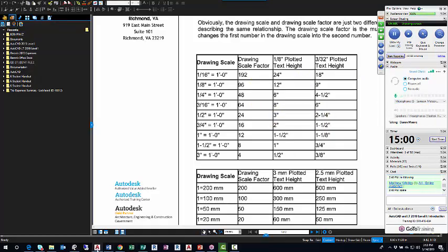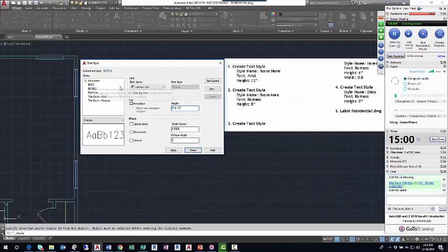So back in AutoCAD, notes, Romans 4.5, width factor 0.8, probably less crucial with a smaller text object. It could stay at a larger size, like a width factor of 1, but I'm going to leave it at 0.8. I'll apply, that saved the change.